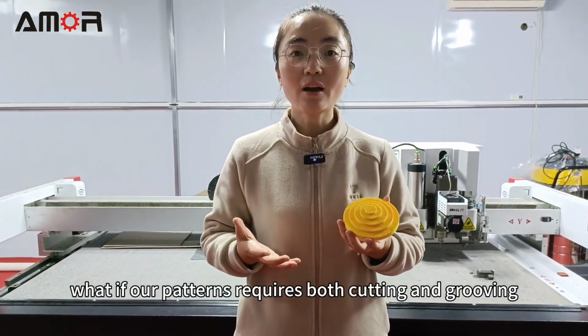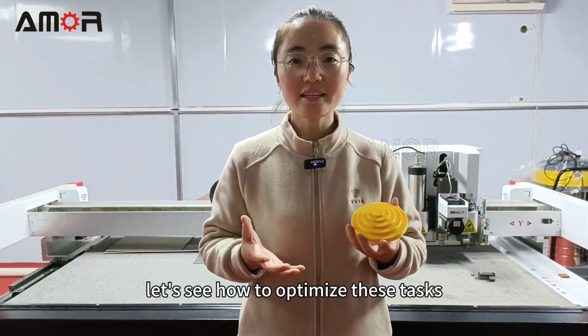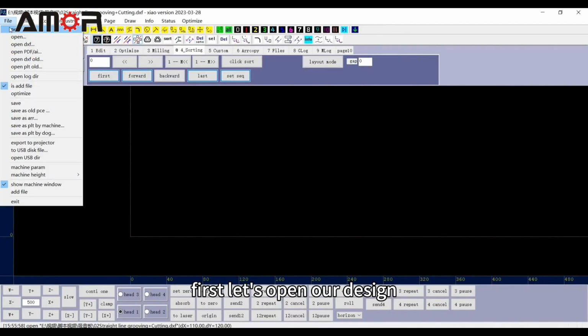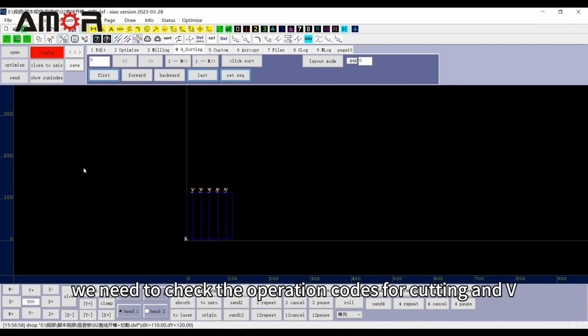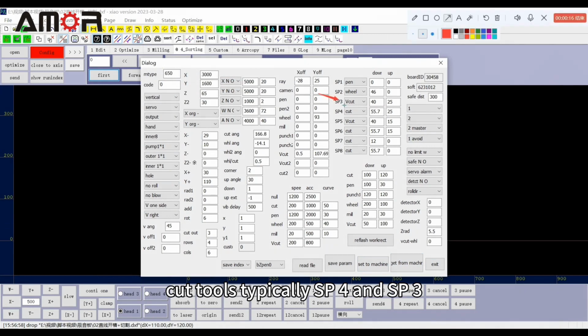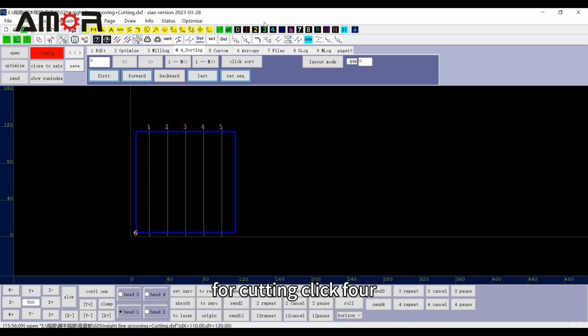But what if our patterns require both cutting and grooving? Let's see how to optimize these tasks. First, let's open our design. We need to check the operation codes for cutting and V-cut tools, typically SP4 and SP3. For grooving, select the desired shape and click the green 3 button. For cutting, click 4.